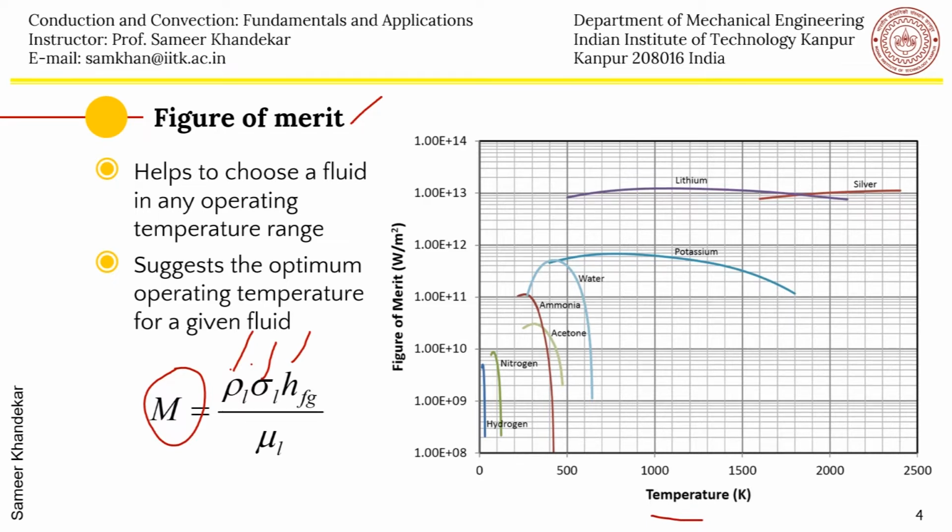and naturally the viscous forces of the two fluids, in which the viscosity of the liquid is the dominating one in the porous media, because the liquid is flowing inside the porous media. So this viscosity of the liquid is the dominating dissipative force, which has to be overcome by the capillary action mostly, because you have to pump the liquid through the porous media. So this sucking of the liquid through the porous media towards the evaporator is done because of the capillary action, which is attributed to the surface tension and the radii of the capillary porous structure.